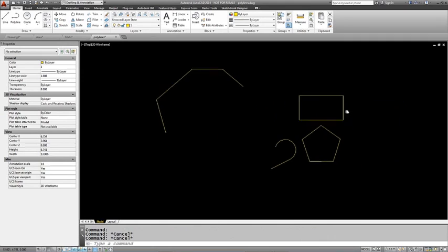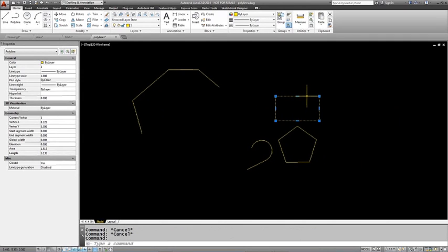On these objects on the right, of course, is a rectangle and a polygon. And rectangles and polygons are polylines. And I can go in and again use the multifunction grips to make any modifications or changes that I would like. If I go to the grip in the center, I can convert that to an arc and change that arc to a different radius for that polyline.